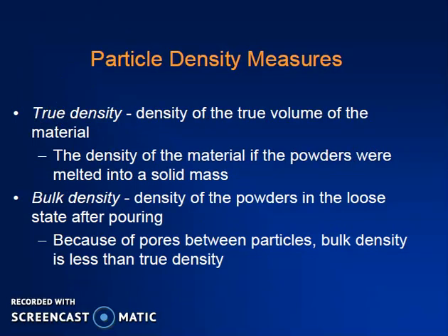Then particle density measures. How to measure the particle density in a volume? True density is the density of the true volume of the material, that is, the density of the material if the powders were melted into a solid mass. And bulk density is the density of the powder in the loose state after pouring. So when you get a loose state after pouring, that is the bulk density of the powder.